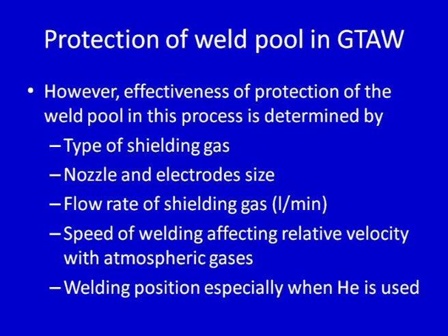If welding is performed at a higher speed, then the atmospheric gases can damage the cover being formed by these gases around the weld pool, and can reduce the protection to the weld pool from these gases. The position of the welding, especially when helium is used.